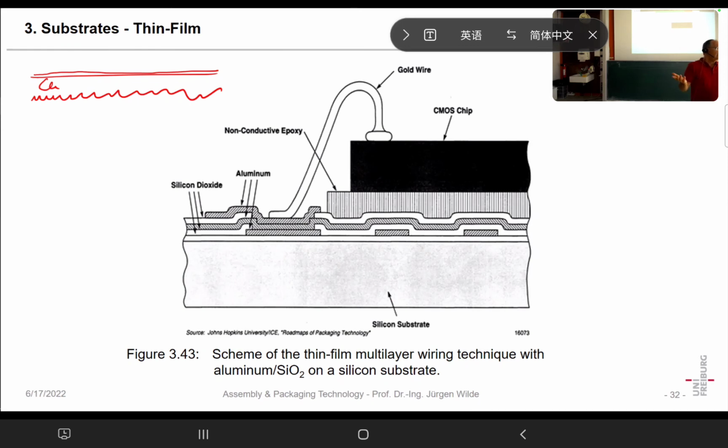What's a material for a high frequency transistor? Gallium nitride or gallium arsenide or such materials, but not silicon. So of course we cannot have monolithic integration. We must have hybrid integration on such a substrate. So what we can use as a substrate that is well available is just silicon.